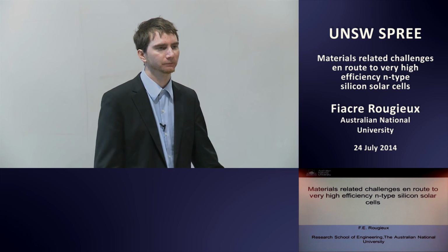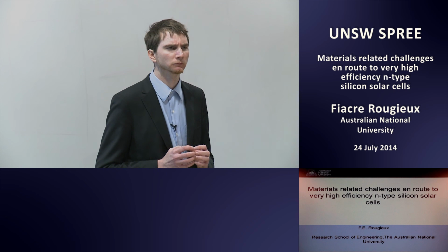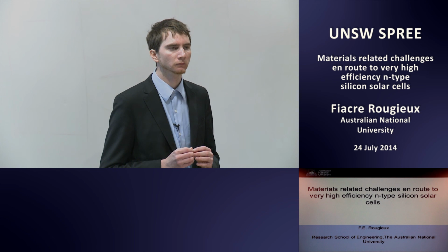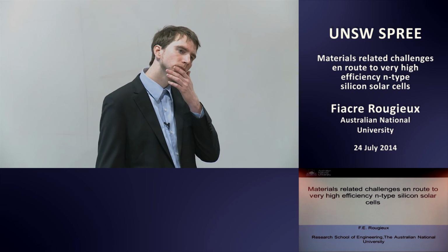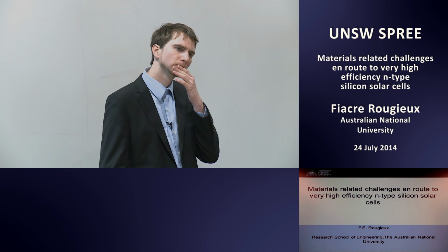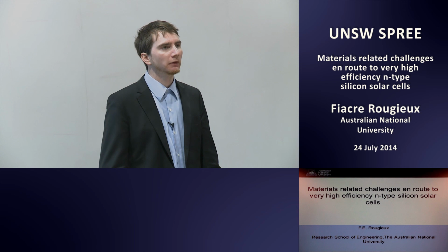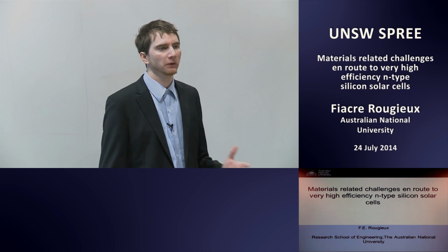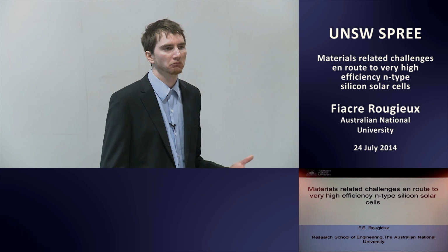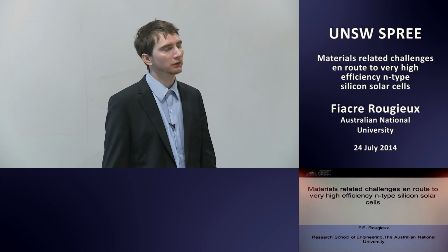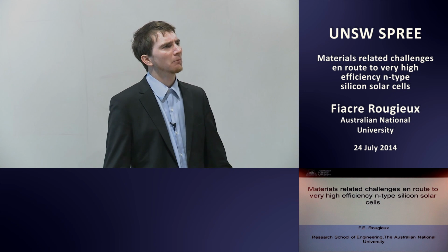Well, in furnaces you use nitrogen as a carrier gas. So you say it's actually not good because nitrogen would then go and create defects, or become recombination-active. Would it be better then to switch to helium or argon or something like that? Potentially, yes, it would be. I mean, for low temperature, the diffusivity of nitrogen can be so low that effectively we're not going to incorporate nitrogen for like 360 degrees or 500 degrees. For the high temperature, potentially we can incorporate more nitrogen, but yeah, it doesn't seem to be a problem.